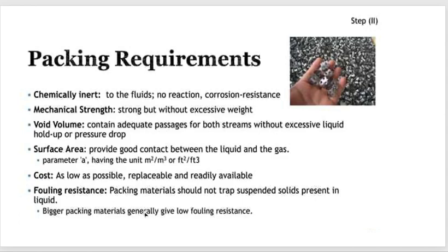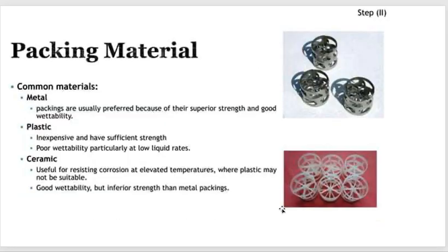Okay, fouling resistance: the packing material should not trap suspended solids present in the liquid. And bigger packing material generally gives low fouling resistance. Here, as you see, this Raschig ring, which composes the packing, common material is metal. Metal packings are usually preferred because of their superior strength and good wettability.